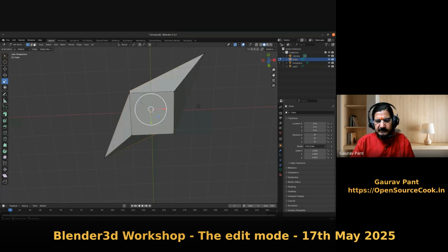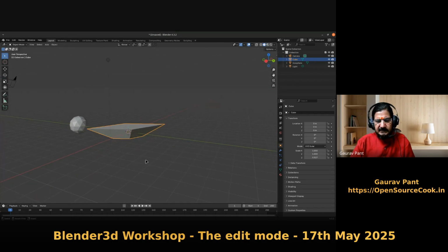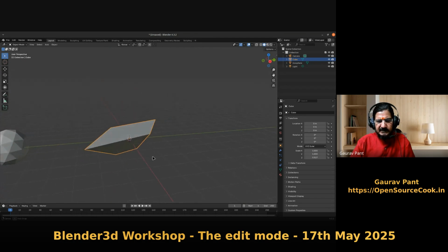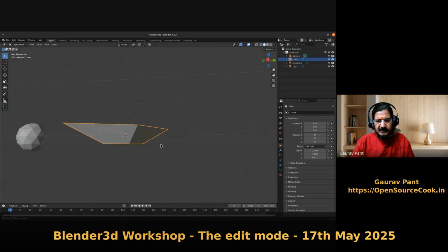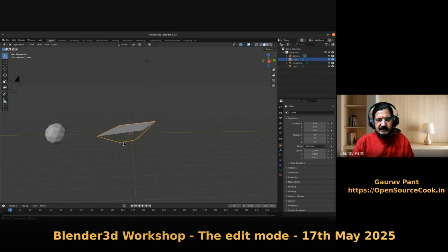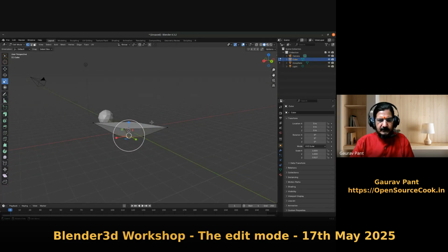And now I will go to the bottom side. I'll grab these two and scale this, fine. I will scale them like this. Okay, so now you see I have achieved a basic boat shape over here. Now no one can say okay, this was a cube, right? We have achieved a boat shape, and a few other operations could make it look more interesting as a boat shape, but the basic shape which I needed, I have been able to edit and convert it into a shape. So that's the purpose of our edit mode, where I have edited this into this particular shape.